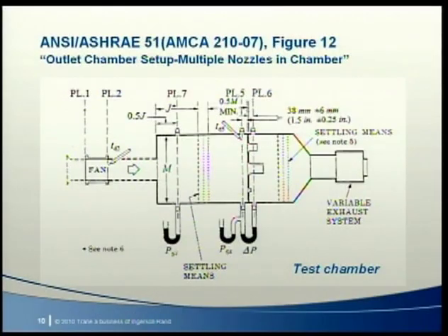Manufacturers determine the shape of specific fan performance curves using laboratory tests defined by industry standards. AMCA Standard 210 explains how to test fans in the lab, how to rate fan performance, and how to construct fan curves from the test data. Many manufacturers use the test configuration shown here. It can produce highly accurate airflow measurements over a wide range of flows, as well as very accurate pressure and power measurements. Tests run using this setup usually provide the most accurate fan performance data available.